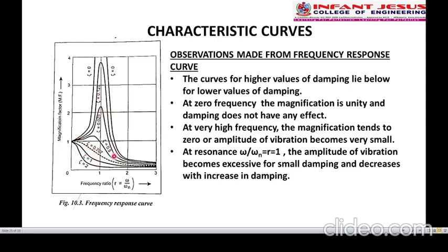From this we have seen so many observations. The higher values of damping lie below the lower values of damping. These are the lower values of damping, and the higher values lie below them. At zero frequency, the magnification is unity. That means the damping has no effect.